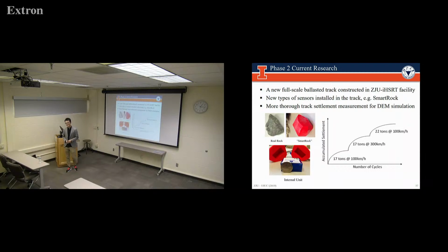Imagine those rocks, again, these are 2 to 3 inch rocks, right? That's fresh ballast. That's how you build the railroad track ballast. What would be the void ratio or density? How can you come up with that correctly, accurately measured in the field from the construction, when you say that the ballast is done, now it is ready for trains?